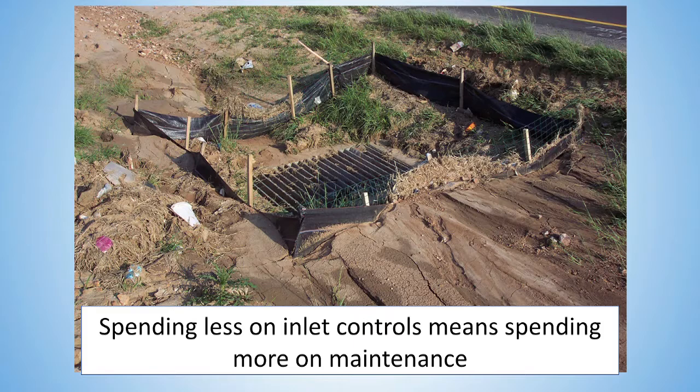Inlet protection devices can only handle about 1 acre of flow coming into them. More than that overwhelms them no matter what the device is. If you're going to use a perimeter control device like silt fence to protect inlets, you have to beef it up. The original specs for perimeter controls are to handle a 1/4 acre of runoff per 100 linear feet of sheet flow. Now I'm putting 4 times more flow in a concentrated area.